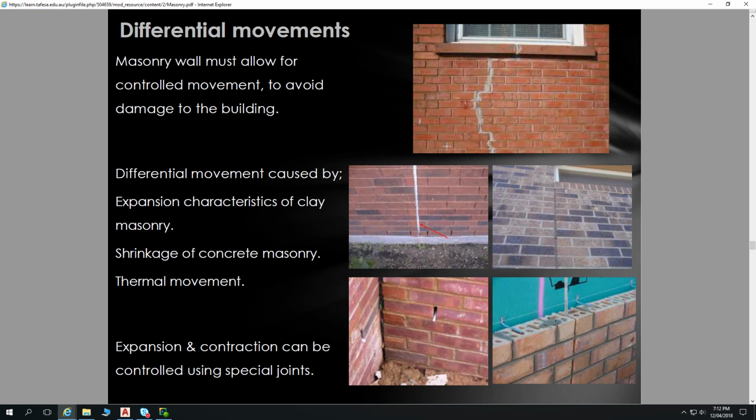So we've got cracks that go straight through brickwork rather than stepping their way through the mortar. It's gone straight through the brickwork. That tells me that there is an exaggerated difference in forces happening in a short space.